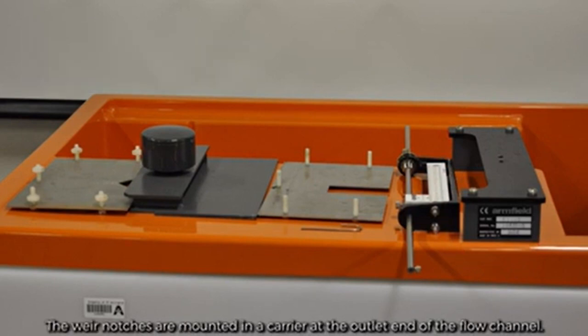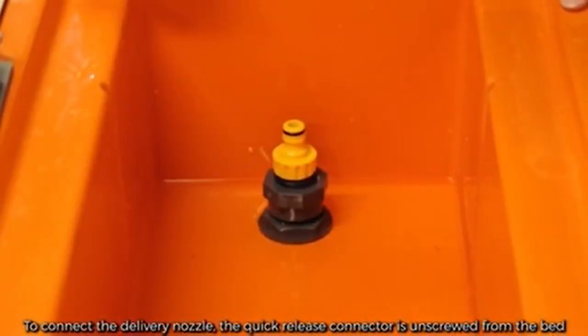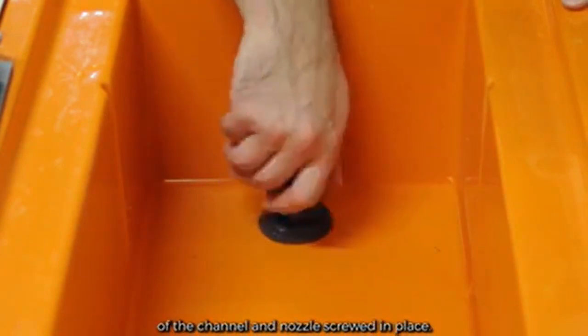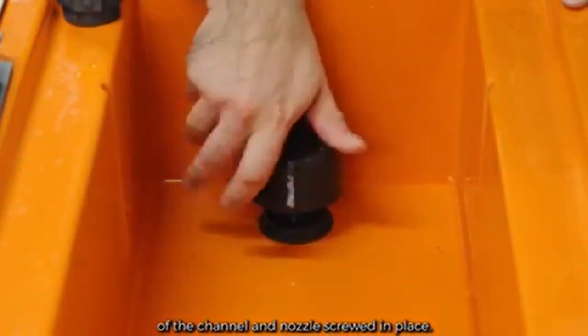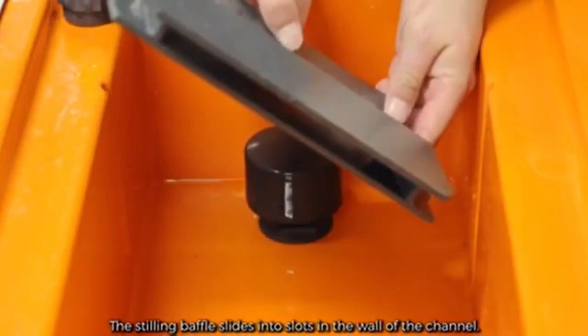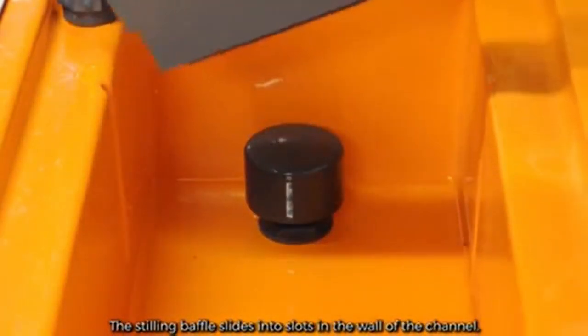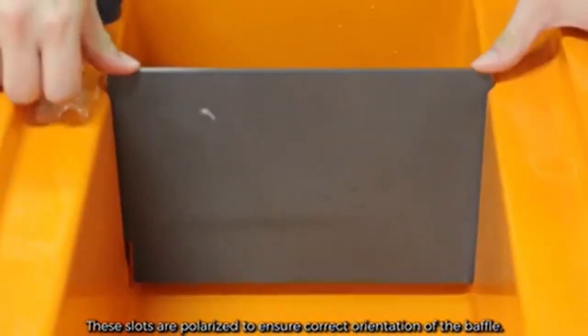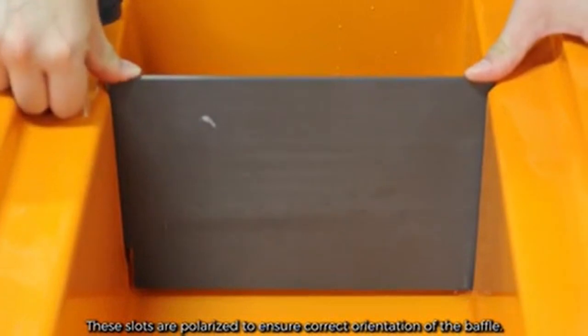The weir notches are mounted in the carrier at the outlet end of the flow channel. To connect the delivery nozzle, the quick release connector is unscrewed from the bed of the channel and the nozzle screwed into place. The stilling baffle slides into the slots in the wall of the channel. These slots are polarized to ensure correct orientation of the baffle.